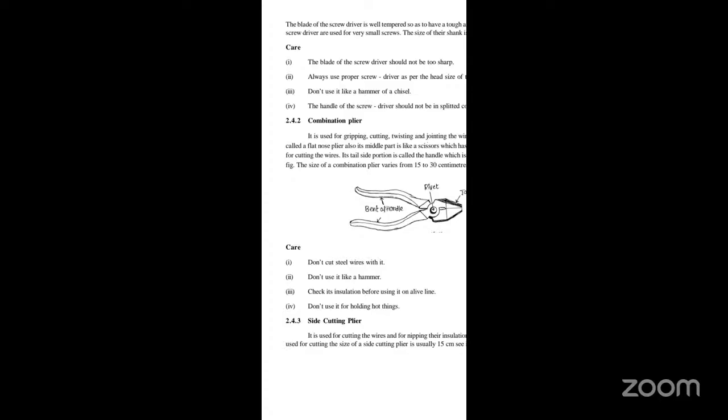Check its insulation before using it on a live line. Don't use it for holding hot things. These are the care points for the combination plier.